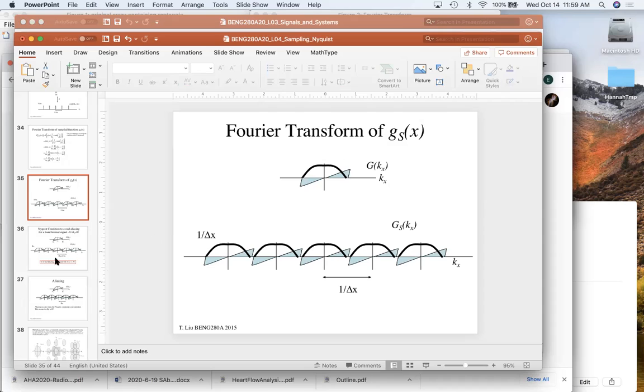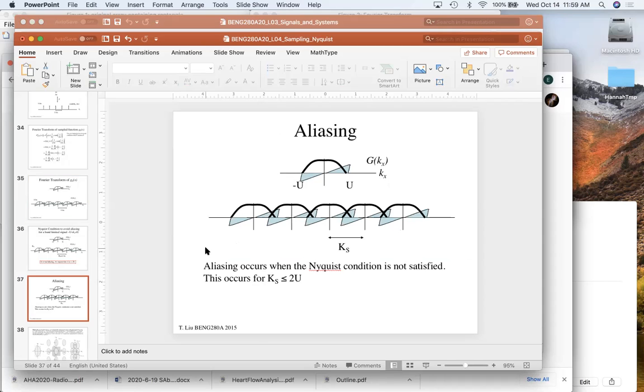But for example, here, the frequencies in the Fourier transform of our object that's been undersampled out here are not going to be accurately represented in our discrete Fourier transform, because of these replicants. However, right here, if this has gone down to 0 by that point and this has gone down to 0, then these components should be okay. So you can estimate lower frequencies in there.